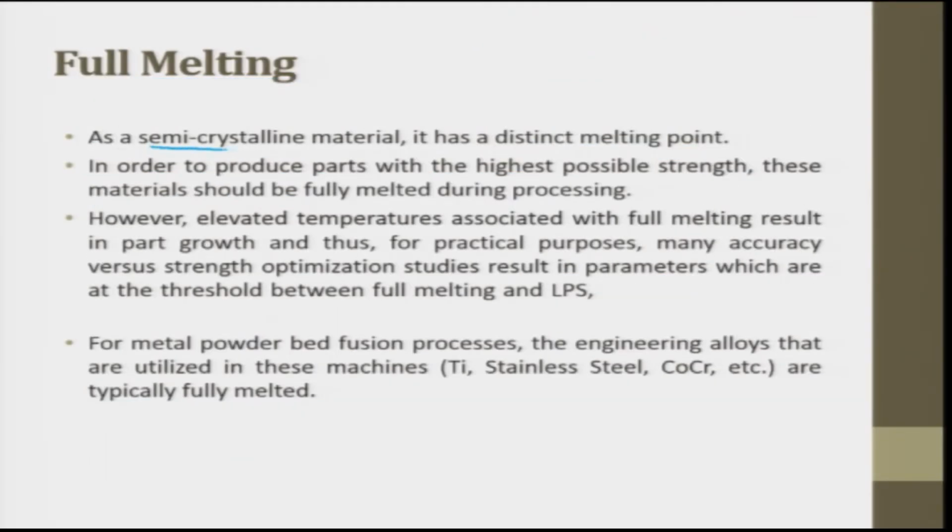As a semi-crystalline material, it has a distinct melting point. Crystalline materials have a distinct melting point, amorphous materials do not. Semi-crystalline is somewhere in between. In order to produce parts with the highest possible strength, these materials should be fully melted during processing.